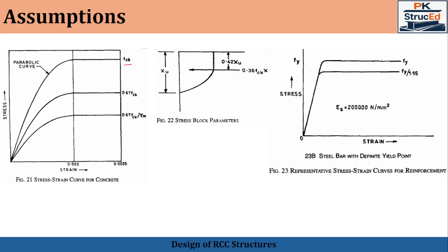The concrete strength in a real structure is less than the cube strength because of plenty of effects. One such effect is the size effect, the shape of the specimen, the casting and the compaction differences, the curing conditions, even though micro cracking may be taking place in the members.